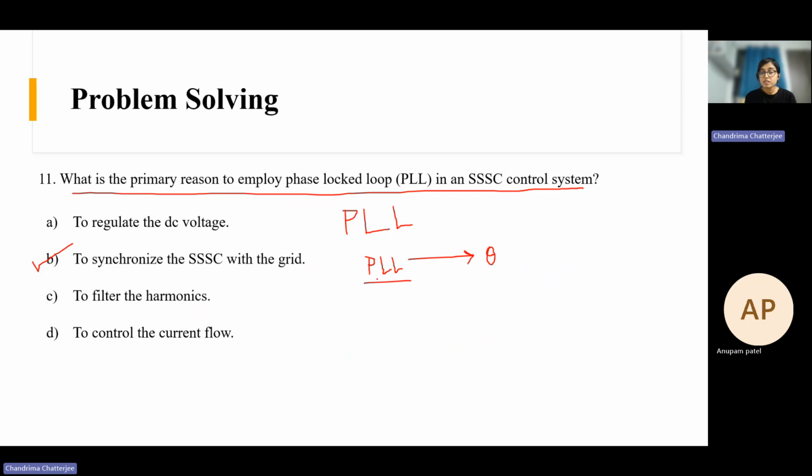So you can always see the block diagram of a PLL where there is a phase detection block. Okay. So suppose these are the inputs, so theta in. There are various elements like phase detection, I am writing PD. Then there is low pass filter.